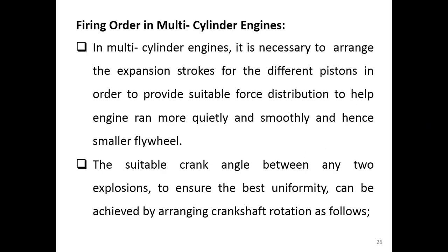When one explosion happens, the second explosion will happen, and we need a suitable crank angle between these two explosions to ensure the best uniformity. And in order to get a suitable crank angle between any two explosions in two cylinders, we can achieve this by arranging the crankshaft rotation as follows.